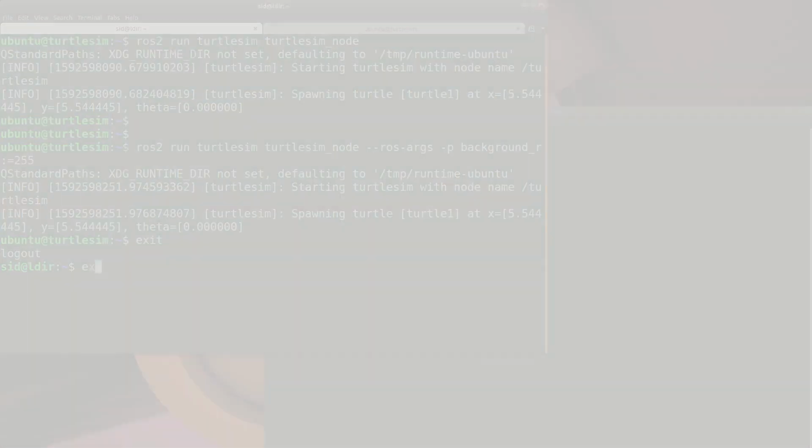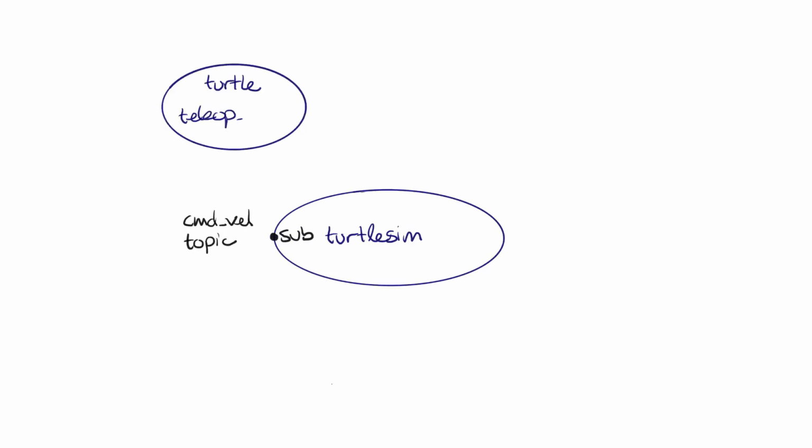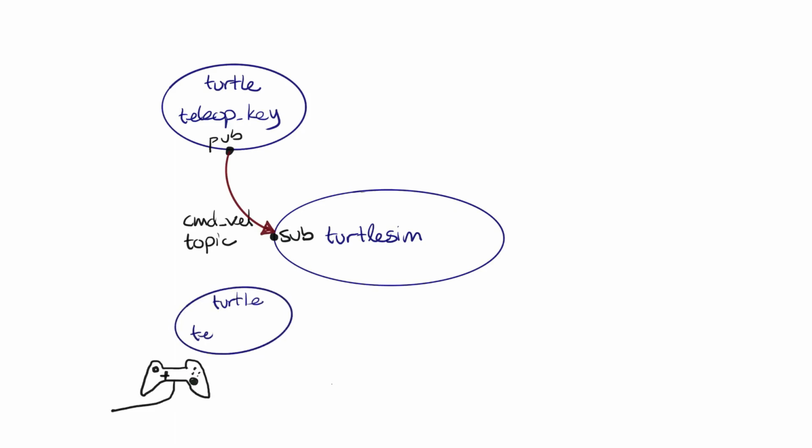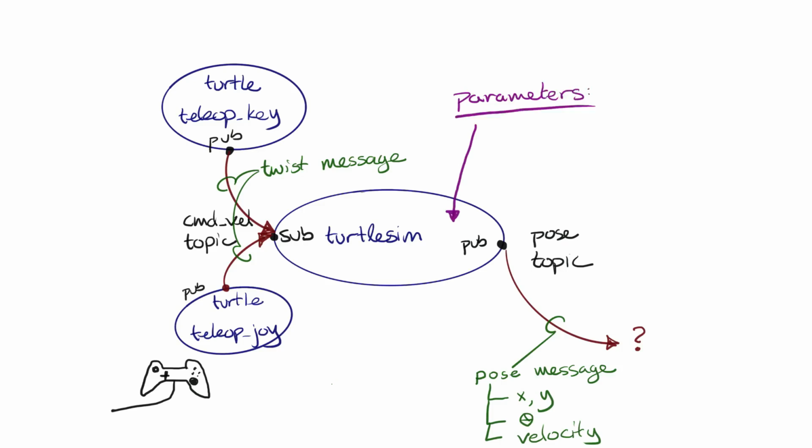We covered a number of concepts, so check out the blog linked in the video comments if you need some more details. And we're only halfway there. We have nodes that can be set up with parameters, and we could string them together with topics and flow data between them. We still need to discuss services, which are a way to get your robot to perform some activity. We also want to cover actions, which are an asynchronous call to define a goal-driven behavior for a robot. But more on that in our next video.